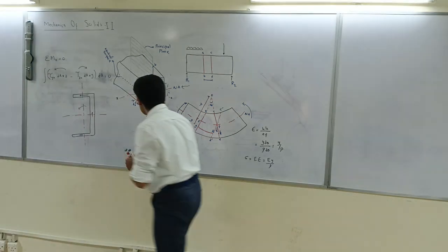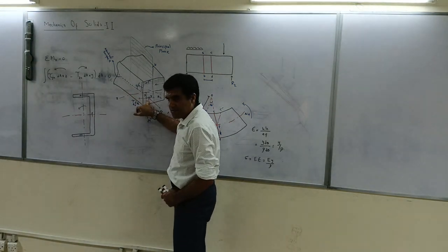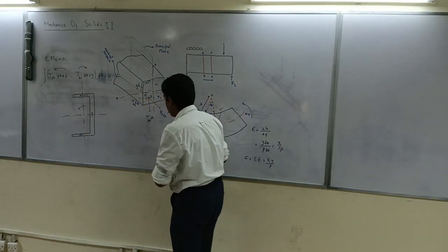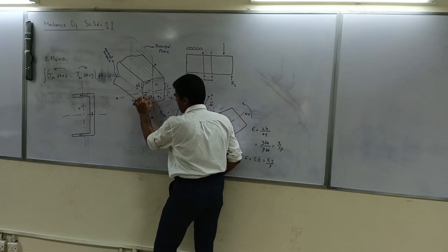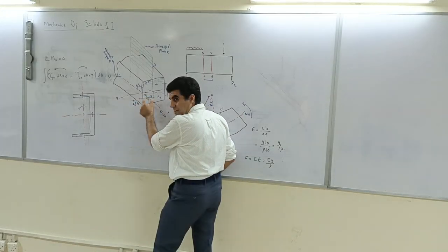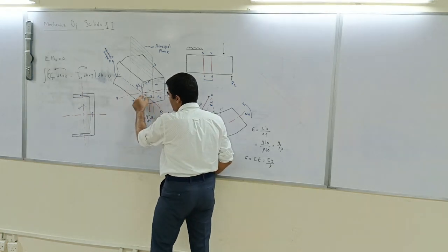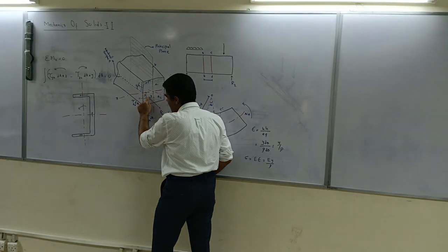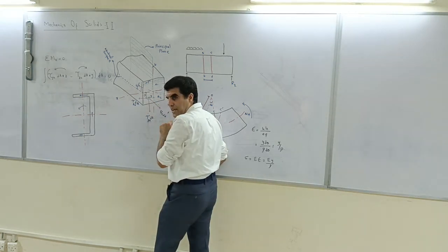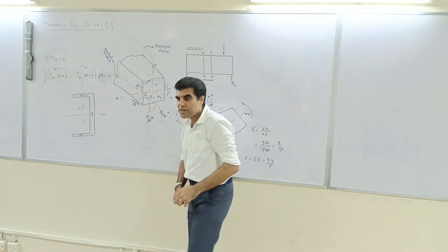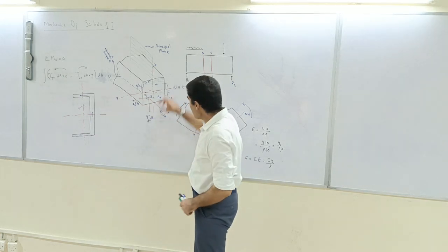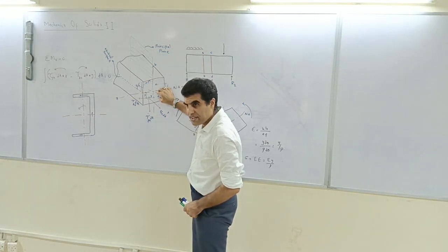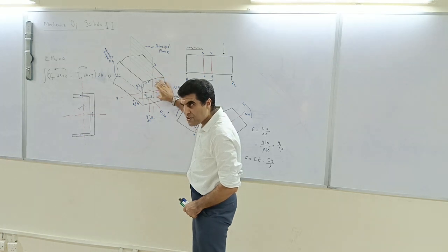Look at this one. We have this element in a rectangular section, and this element will cause a moment of this times z. Agree? And similarly, this element will cause a moment of this times y. Now you have exactly the same type of element at the top. You add them up, they both come out to be 0. Similarly, you can have an element over here and an element over here. You sum them up, you will get 0.